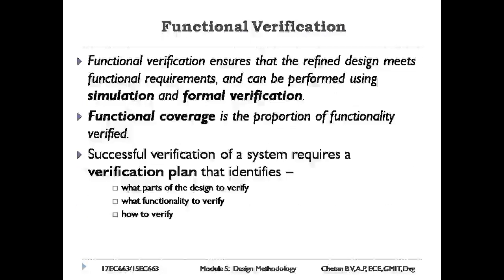Functional verification. Functional verification ensures that the refined design meets functional requirements and can be performed using simulation and formal verification. Functional coverage is the proportion of functionality verified. Successful verification of a system requires a verification plan that identifies: number 1, what parts of the design to verify; number 2, what functionality to verify; number 3, how to verify.